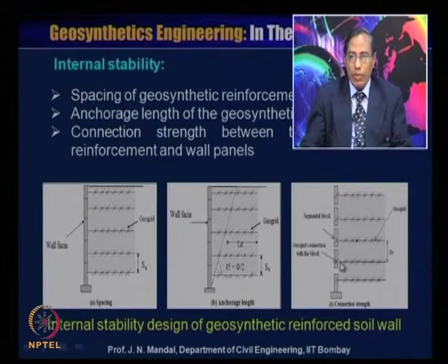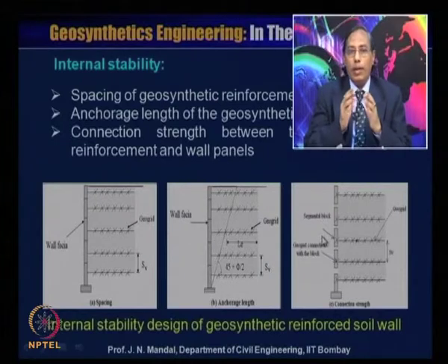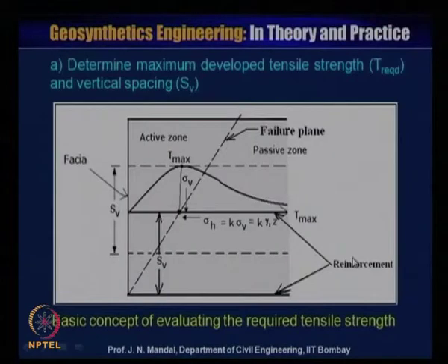This you can see, how the geogrid is connected with the panel or the block. So this is a segmented block, and the geogrid is connected with this, so there is a possibility for failure. So all these you have to check. So determine the maximum developed tensile strength T required and the vertical spacing.